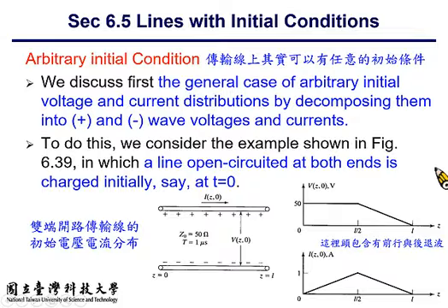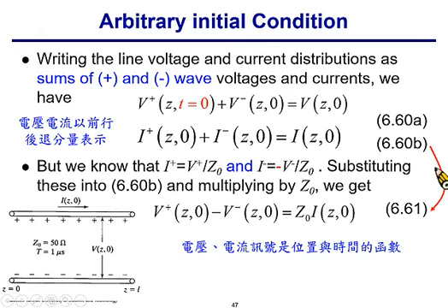On the other hand, if you terminate it with shorts at the two ends, what is the boundary condition required? That will be the voltage: if they are short-ended, the voltage here should be 0, and the voltage here should be 0 as well. So before you proceed with the problem, you should check the boundary condition. And this problem looks fine.